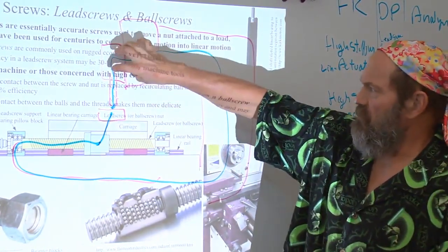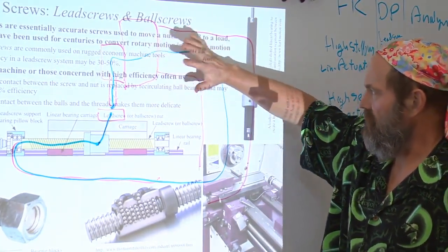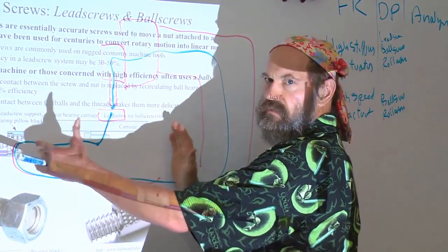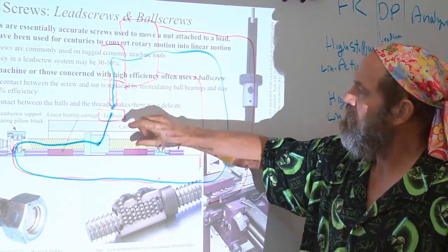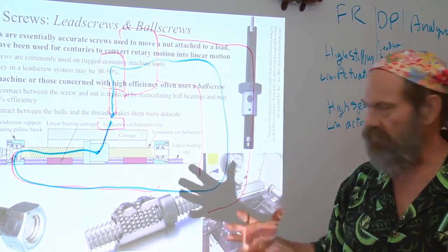This is a big, powerful spindle, big, powerful axes. Notice the axis is in compression here, so when you're pushing this way, you're not compressing the screw. You have a lot of cast iron. The tool might be bending, but let's make this a real heavy, thick carbide shaft.